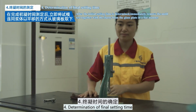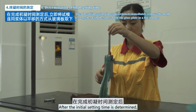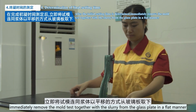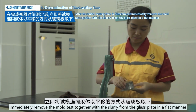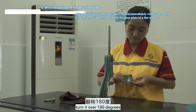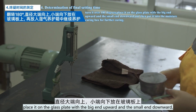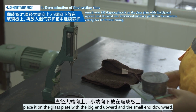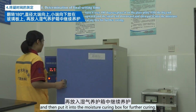4. Determination of final setting time. After the initial setting time is determined, immediately remove the test mold together with the paste from the glass plate in a flat manner. Turn it over 180 degrees and place it on the glass plate with the big end upward and the small end downward. Then put it into the moist curing box for further curing.